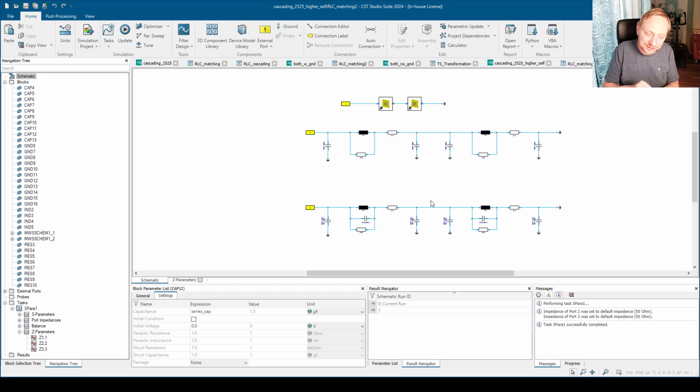What are the effects? The main point here was you receive this file telling you that this is the measurement of an inductor. But inside this Touchstone file, there are a lot of capacitances to ground, which come from the signal trace and not from the inductors.